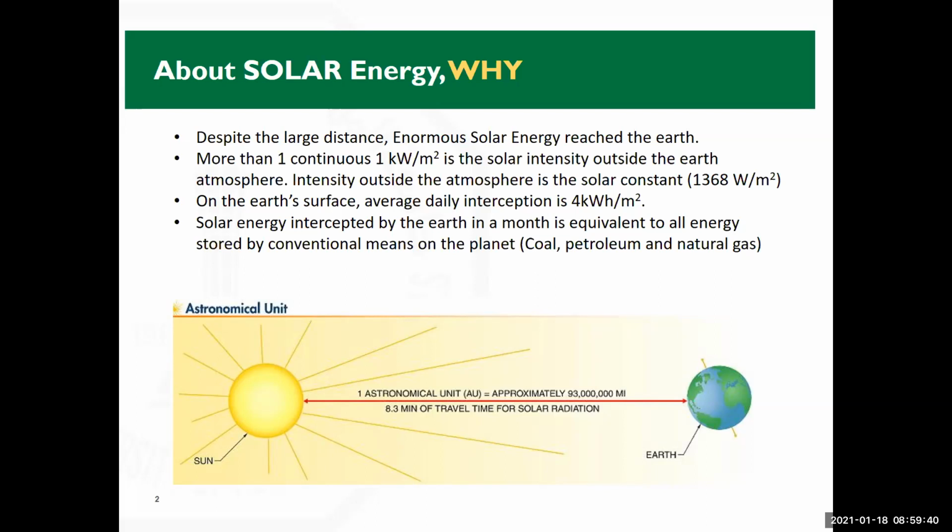So the answer is that up there, it is the rate of energy, which is energy per unit time. This is watts. Watts is joule per second. But the second one is energy times time, so kilowatt hour. We can even convert that into kilojoule easily, because the hour is 3,600 seconds. So I can convert that into kilowatt second, which is a kilojoule. So here we have the quantity of the energy or the rate of the energy multiplied by the time.